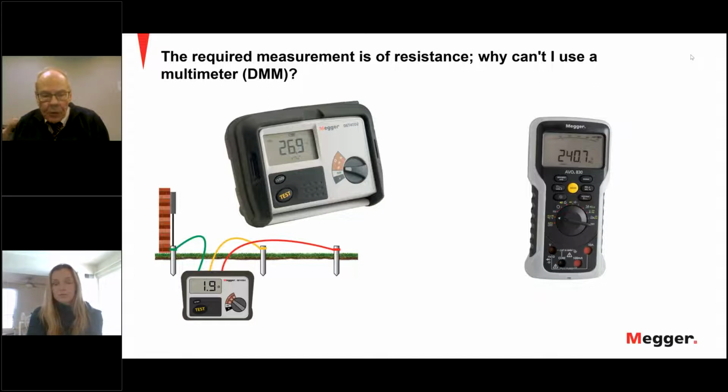All these computer rooms and offices, they're chopping up the sine wave, and they're using what they need to run their computers, narrow voltage DC, and they're putting the rest of that back on the grounding system. A lot of that is with the parallel grounded neutral. A lot of that's getting back into the soil, and it's got to go back where it came from, the transformer that is feeding your site. And so that's going to get into your measurement with a DMM.